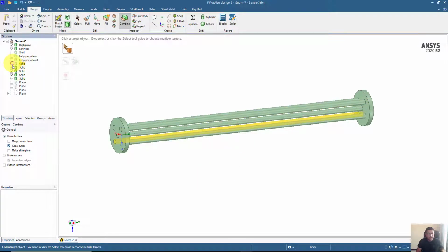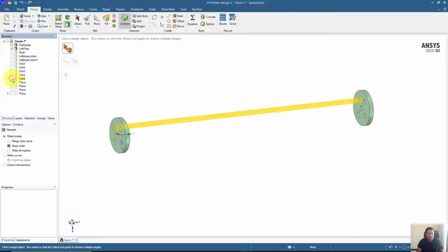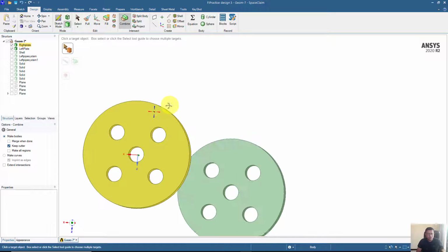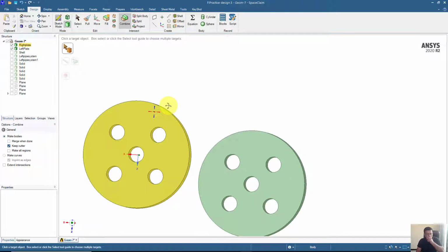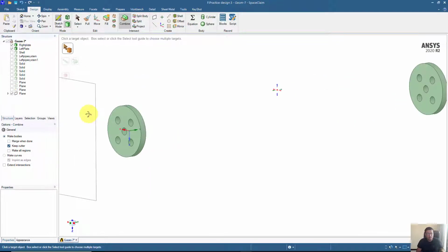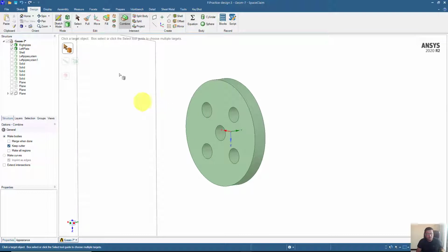So if I hide these 5 solid bodies, the 5 tubes, now you can see that we have this thing with us. So now they have the opening for these 5 tubes. One more thing is that I think we first have to make the thickness of the tube. So once we apply the operation, this will be through all the plates, all the systems like the shell and the left and the right header. But anyhow, this will just add one additional step.